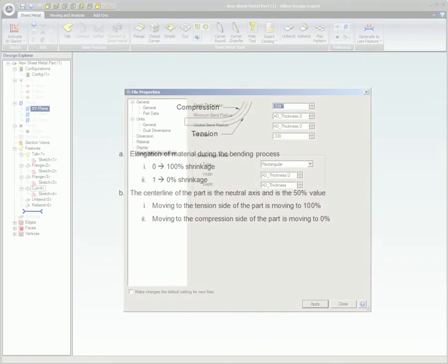This image shows what happens when a flange is created in the physical world. Since most sheet metal manufacturers have their own set of values they use for the K-factor, make sure you use the same value they use. K-factors can be different depending upon the type of material being used, the intent of the design, and the type of equipment being used to bend the metal.